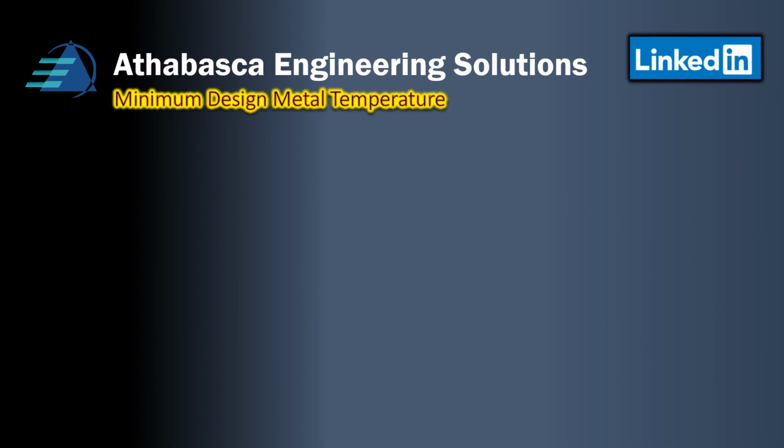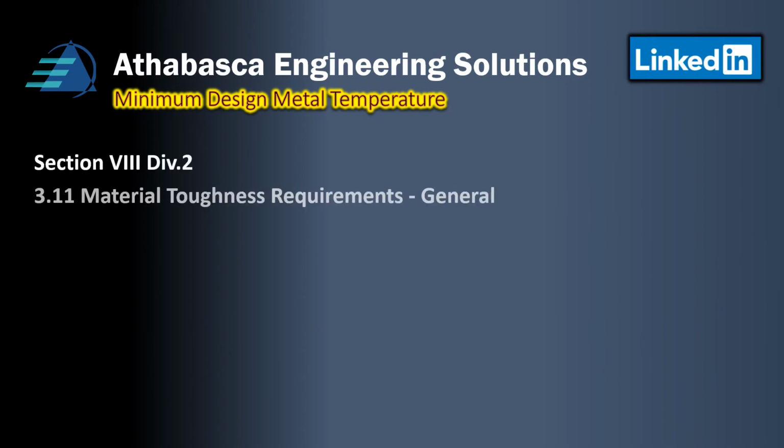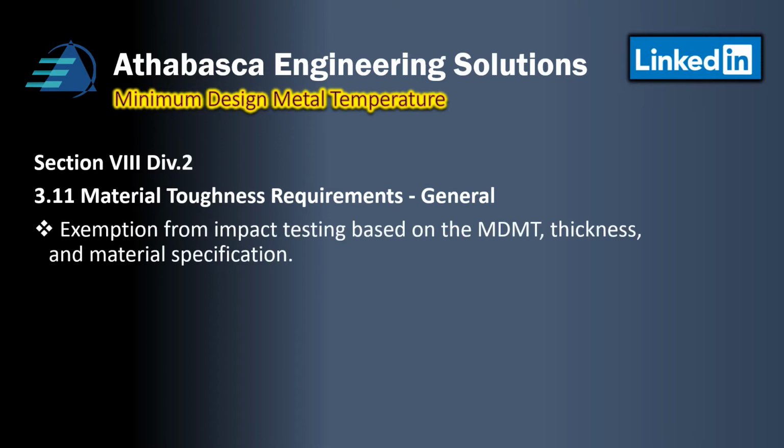So let's look at the Division 2 material toughness requirements as quoted in 3.11. Basically, what they're saying is that Charpy V-notch impact testing shall be made for materials used for shells, heads, nozzles, and other pressure containing component parts, as well as structural members attached for structural integrity of the vessel.